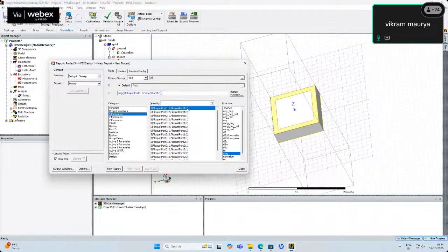The second term represents its polarization, like this is mode 1 to the same mode, and this is port mode 1 to mode 2. There is a cross polarization between these two terms. Both of these terms are S11 only, because the input is Floquet port 1 and the output is Floquet port 1 only, but this is 1 to 1 polarization reflection and this is 1 to 2 reflection.